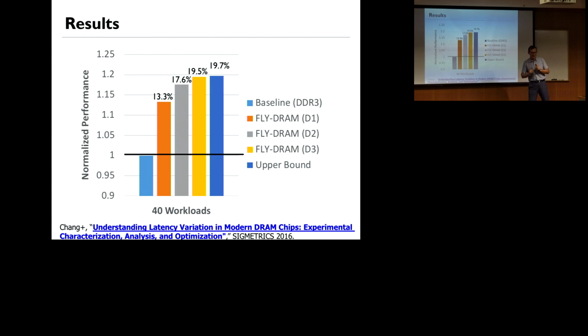Yeah. It's reactive action according to the address. It's not like you try to optimize accesses. So the latency of the table, I think that's not going to be very large, but you can overlap it because there's queuing that happens in the memory controller, and you can overlap it with everything else that goes in the memory controller. It's more throughput, and it's also the size of the design of the table, basically.